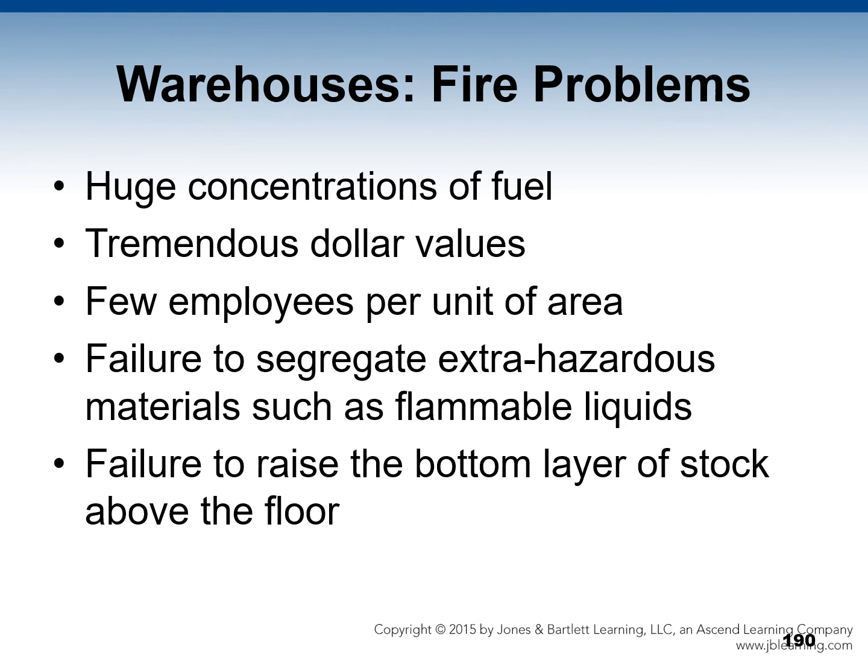Some warehouse fire problems. You have factors that contribute to warehouse fires. You often have a huge concentration of fuel. Tremendous dollar values are collected in these warehouses. Often you have few employees per unit of area. Sometimes in warehouses you have failure to segregate extra hazardous materials such as flammable liquids. Sometimes also there's a failure to raise the bottom layer of stock above the floor, thereby preventing water damage and possible collapse.